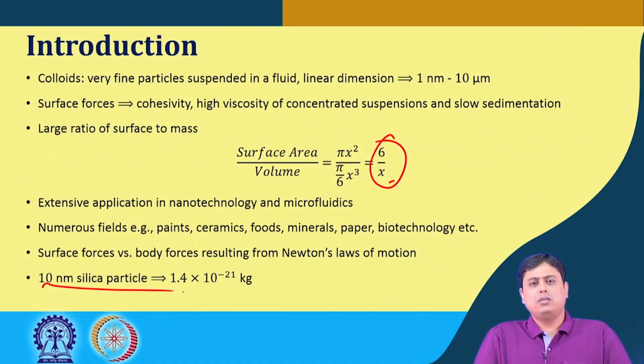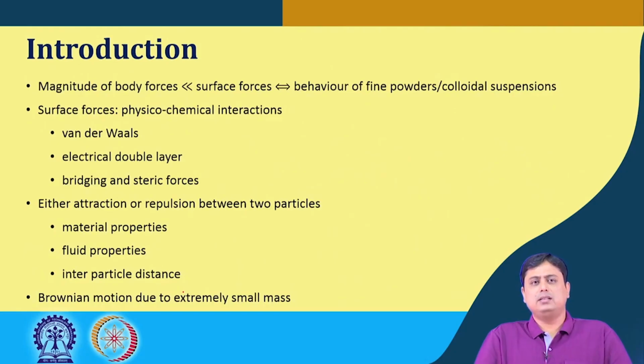It depends on the surface property, material property, the intervening fluid property, etc. Whereas the body force is relatively easier to understand, and that is why we will see in this section in a bit of detail what are the surface forces that actually dictate this behavior of the fine particles or the colloids.